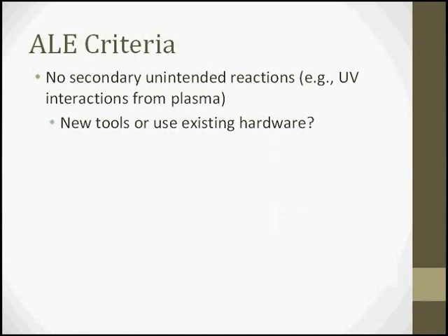Neutral beam etching introduces a high aspect ratio grid that neutralizes electrically the ions as they pass through by having specular collisions with the charged grid walls that neutralize their charge, but they still maintain their vertical oriented kinetic energy heading and still strike the wafer. So this can provide a more controlled physical desorption step. And it also separates the UV exposure from the wafer by introducing this grid array, or by using a downstream plasma for the radical generation.